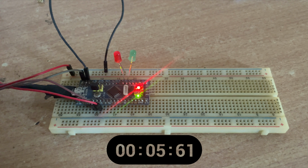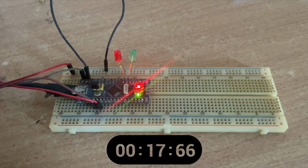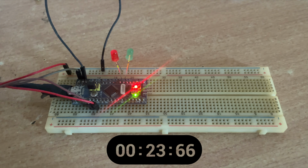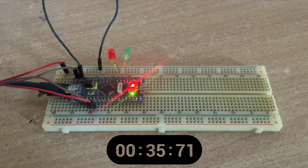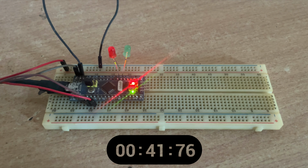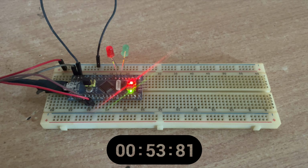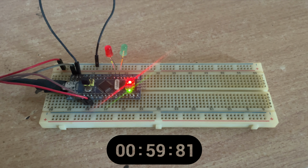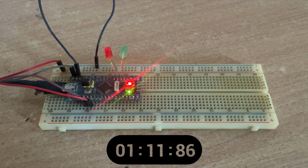Even after switching to LSE, the alarm is not triggering properly. This is because I'm using a cheap STM32 board, like the Blue Pill. So even though LSE is selected, the crystal is either unstable, not oscillating correctly, or completely unreliable. As a result, the alarm timing is inconsistent. Sometimes it drifts. Sometimes it doesn't trigger at all. This is not a software issue.